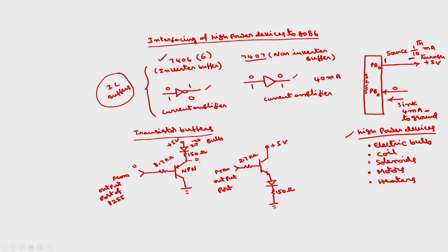But here we are going to amplify the currents. So the current passed through this LED will be more, and LEDs can even be replaced with bulbs. In that case, accordingly you have to take these voltages. Bulb means we require larger voltages. The current capacity of this buffer is 40 milliamps, whereas using this transistor buffer we can go up to 400 milliamps currents.